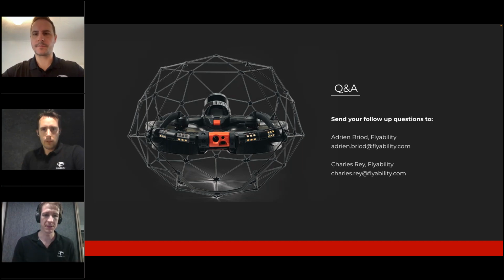Yeah, so the answer is yes, you can on GeoSLAM Connect. And even very soon, if you have targets in these models, which are scanned in the two scans, it will even automatically align. While today you need to do a little bit of manual coarse alignment before there's a refined automatic alignment.